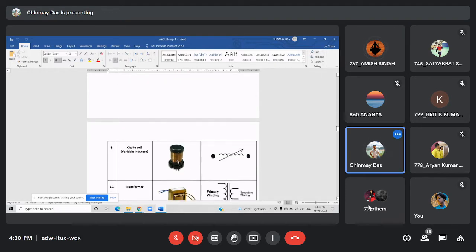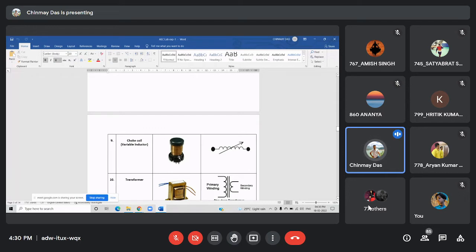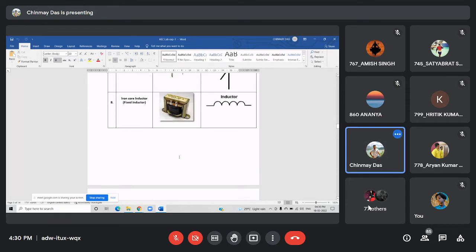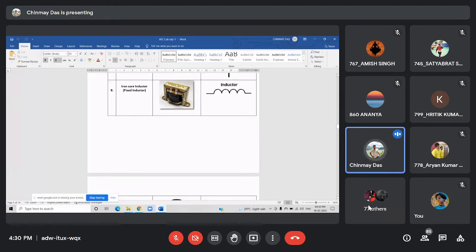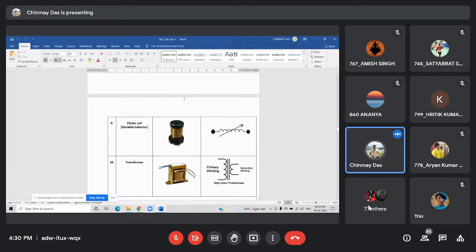Normally the inductance value depends on the amount of flux: the more turns, the more flux is generated, and the flux passes through that core. In this iron core, the flux will be more efficient and losses will be less, because the flux will be in a bound area for that iron core. Now in this variable core, what will happen? There will be a vertical or cylindrical core inside, suppose a ferrite core. As I said, the core is responsible for holding that flux around it. If you move that core out, suppose halfway, the flux value will decrease and accordingly your inductance value will change.